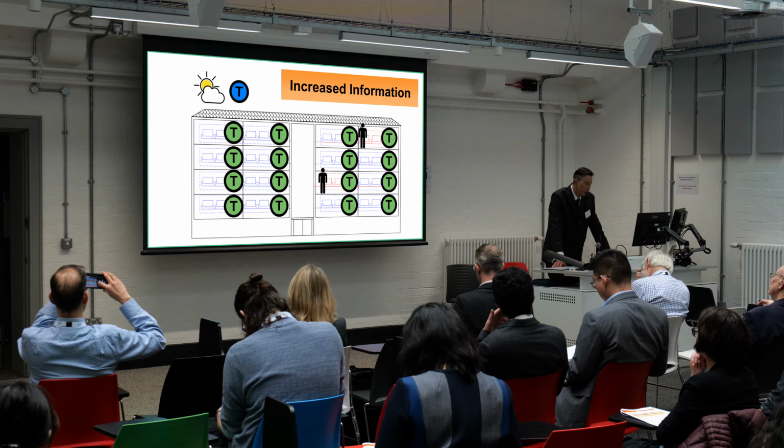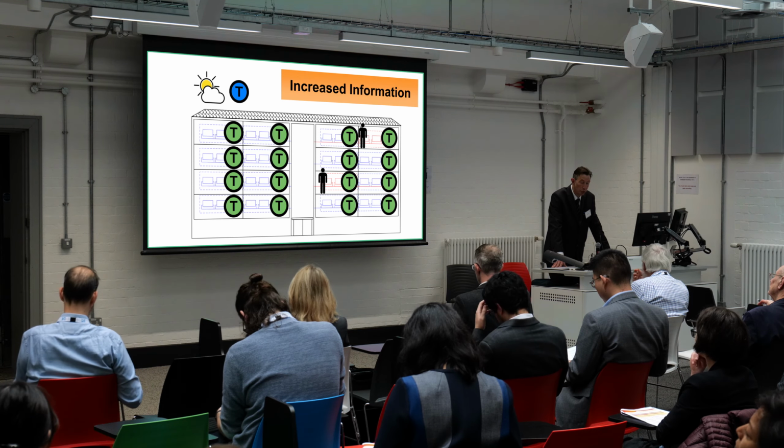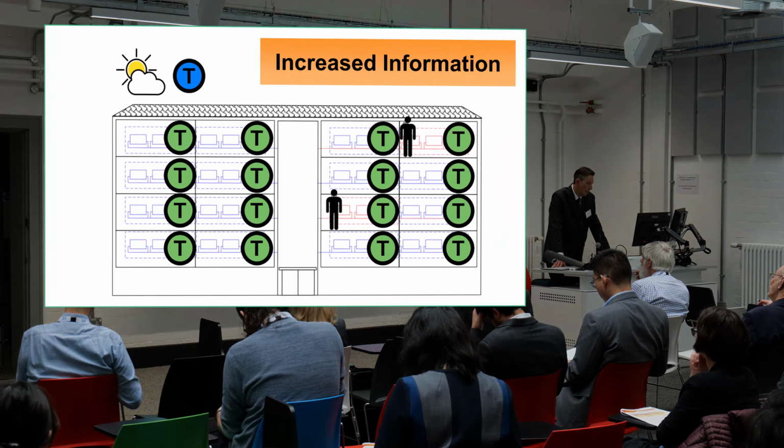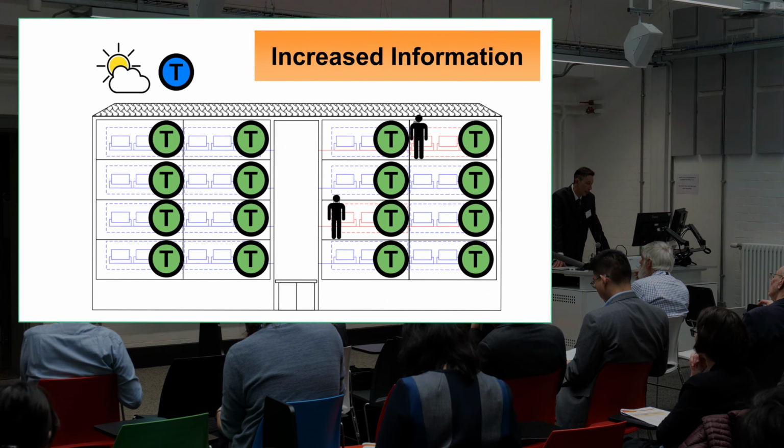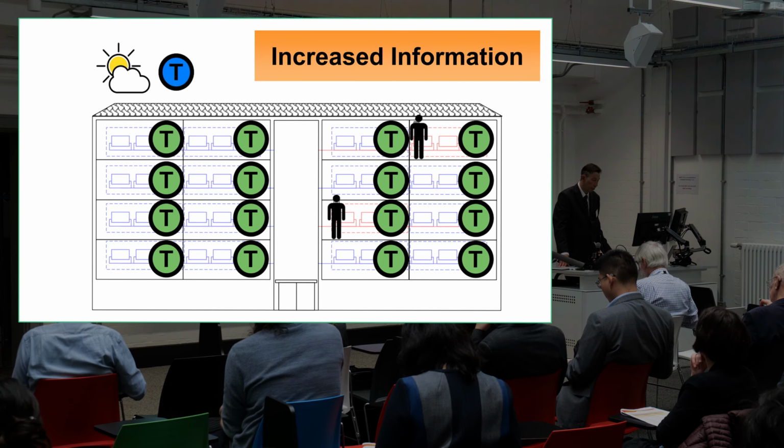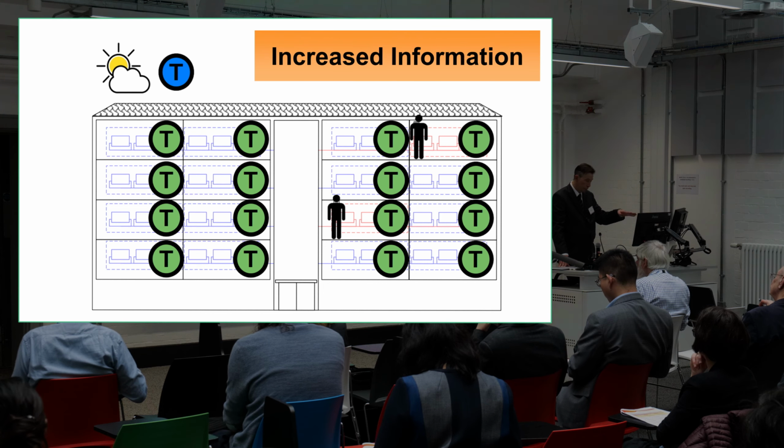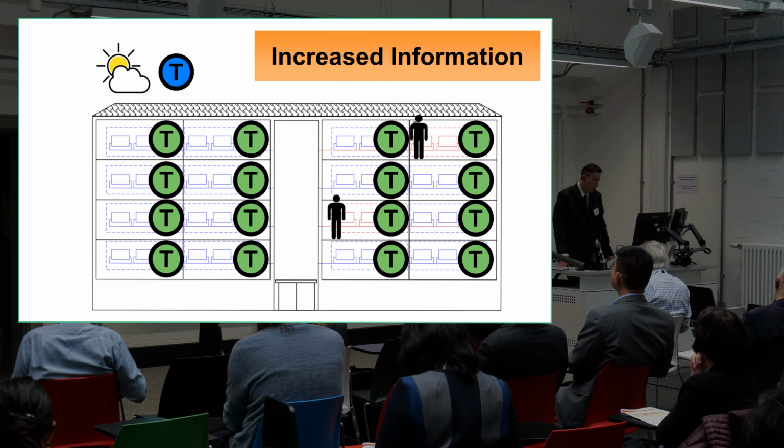So let's take our building and add some more sensors. For every occupied zone, we're going to add a temperature and a motion sensor. And we're going to replace the mechanical TRVs with smart TRVs, which gives us the ability to remotely adjust the set points of the TRVs. So for example, between a frost level, setback, occupied target temperatures.